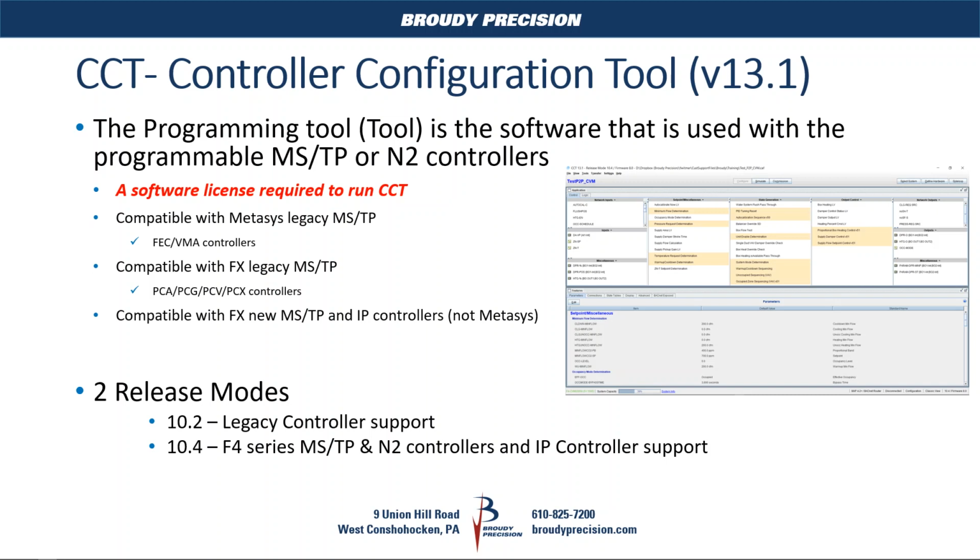And with that, the tool has two release modes: a 10.2 mode and a 10.4 mode. The 10.2 mode is used to program and work with the legacy controllers, meaning the FX legacy, PCA, PCG, PCB type controllers. Also with CCT 10.2 mode, it will allow you to work with the Metasys legacy MSTP controllers as well.